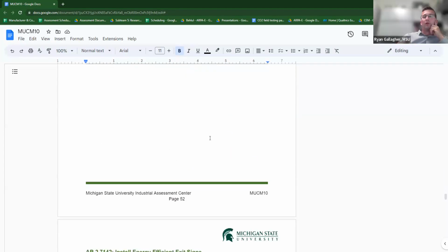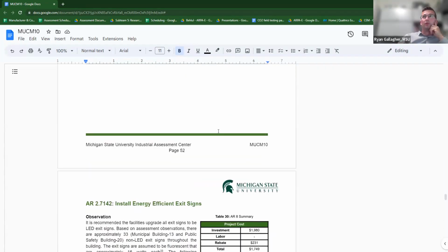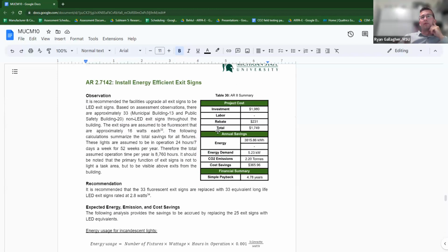Right. And if you have one box that serves multiple rooms, which I think you guys do, which is pretty common for us on campus as well, you have to have an occupancy sensor in every single room that box serves. If any room is occupied, then all the rooms become occupied for that VAV box. So that becomes a little bit of an issue.